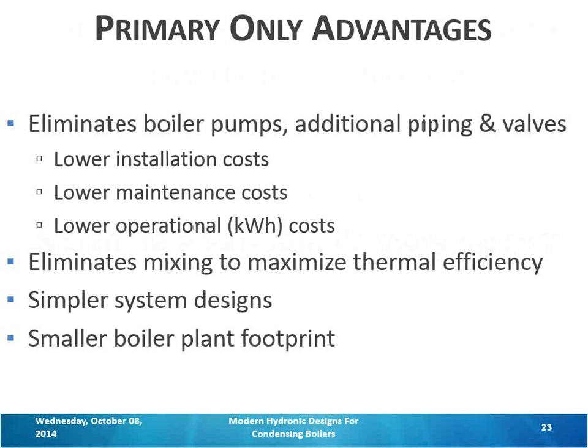And we're going to select 3 high-mass and high-volume condensing boilers and put them into a primary only setup. These will be 2 million BTU an hour input apiece, and that gives us an N+1 design in terms of the output. So if we lose any one boiler in that sequence, we can still provide all the heat we need to keep that building comfortable on the design day. Now, sometimes that's overkill, but depending on the design, that may be required. So in this example, it is.